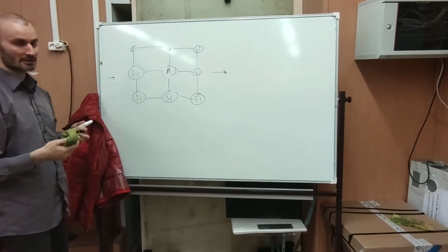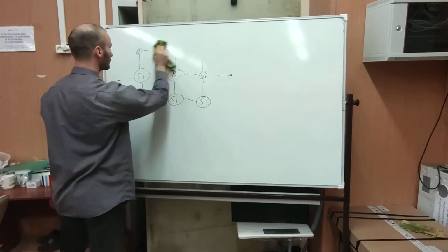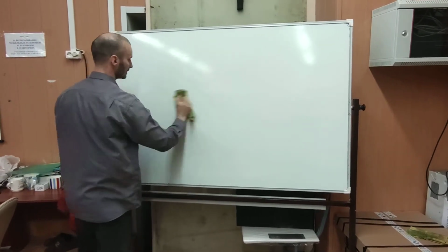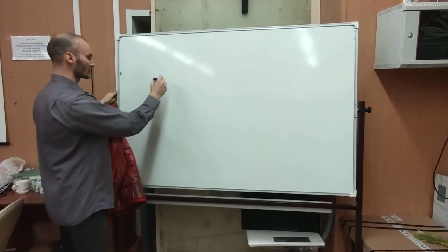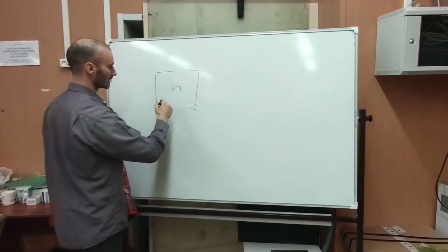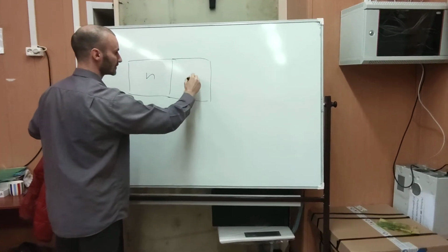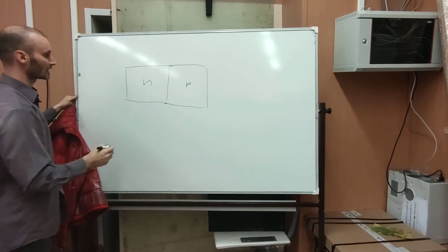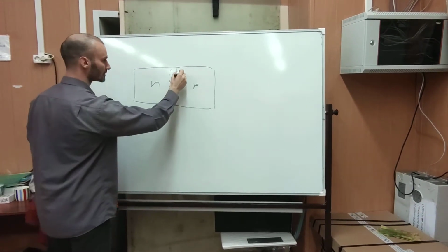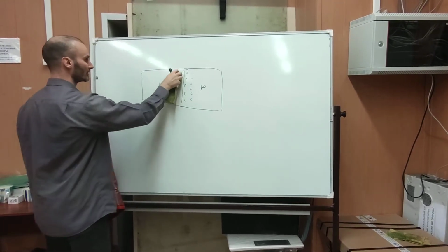Okay, so now let's see how we can make an electronic switch. Oh no! First let's see how we can make a diode, using several types of doping. Okay, so we have n-type doping, which is phosphorus rich, and we have p-type doping, which is boron rich. So what happens is we have some holes here. Sorry, we have holes here on this side, and we have electrons here.